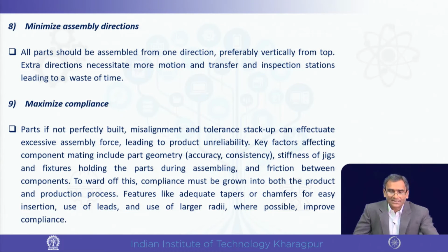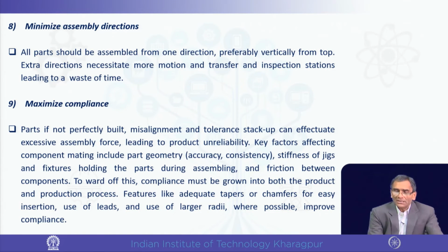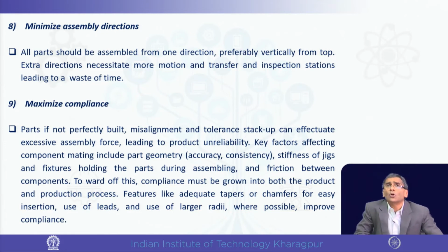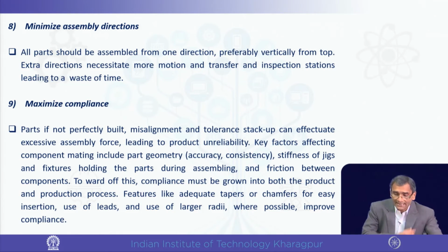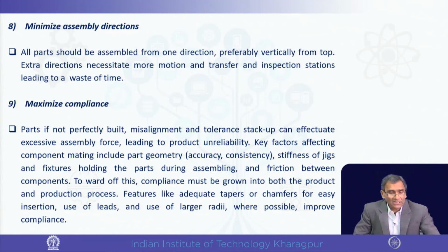Maximize compliance. The tolerance or alignment should be such that the assembly becomes easier, so unnecessarily stacking up tolerance should be avoided. Also, the jigs and fixtures should be tough enough and stiff enough so that bending does not happen, and so the compliance takes place.